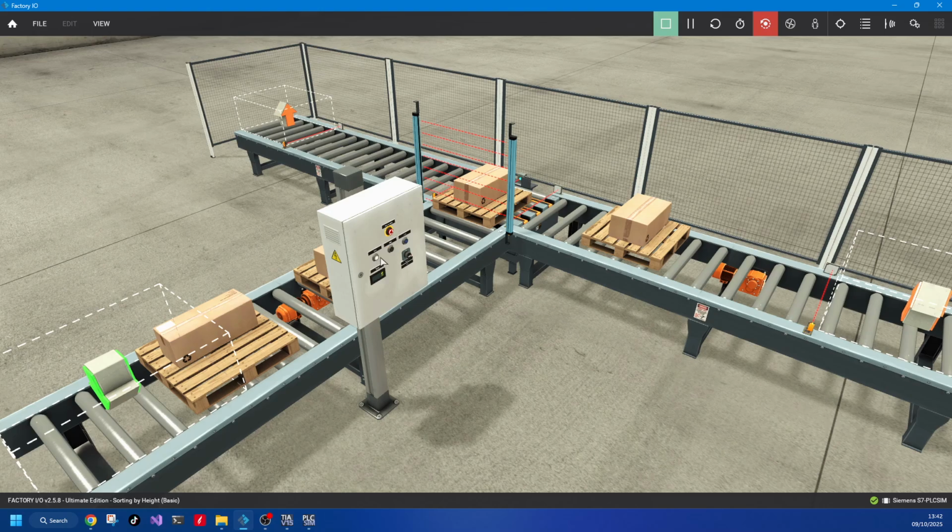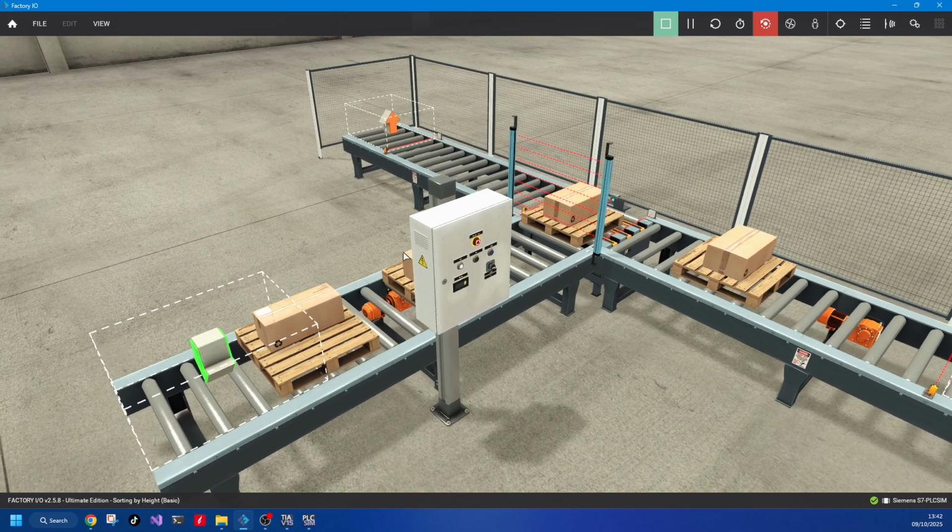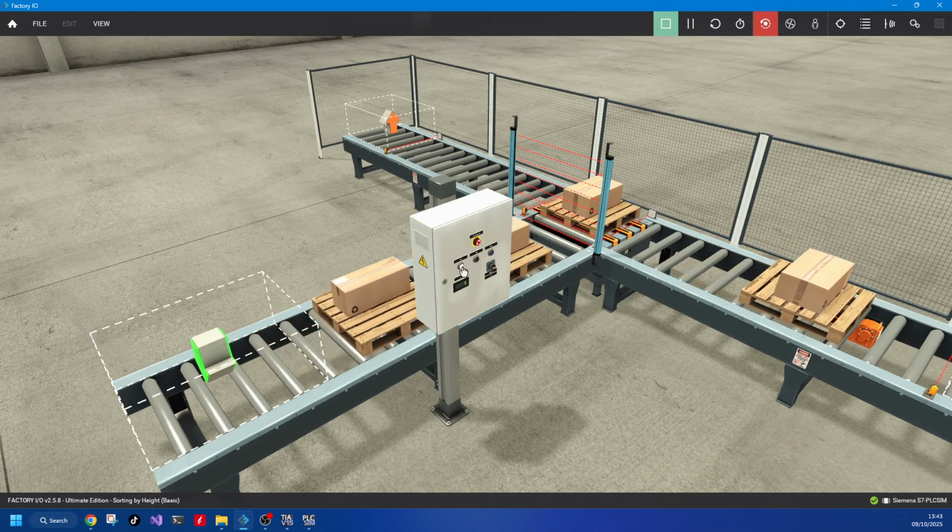Now, I can't start, can't stop, can't do anything because the E-stop's still activated. Again, have a look at the code. It's all there. Release the E-stop, press start, does nothing. So, again, the condition is we need to go into manual, into auto, and then we can hit start. And we should resume.